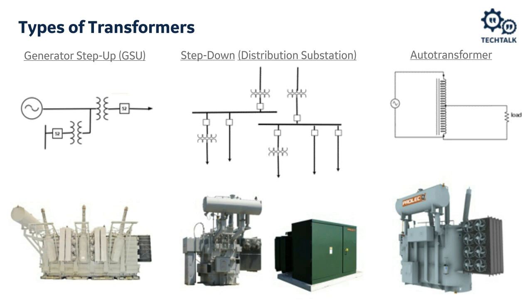Lastly, we could also have an auto transformer, which we show on the right here. We don't see these as often, but they do have some advantages, like they're smaller since they only have one winding. They're more efficient. You can effectively change the ratio by tapping it at various points, and overall, they're usually cheaper. However, because there is only one winding, there's no electrical isolation between the two sides.